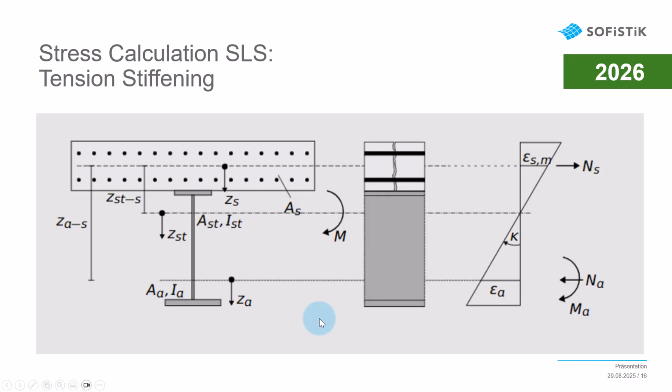First, a short reminder what it is about. In a reinforced concrete slab acting in tension, the concrete in between the cracks still takes part in transmitting the forces in the slab. So even if the slab is cracked, it is stiffer than the pure reinforcements in the slab.